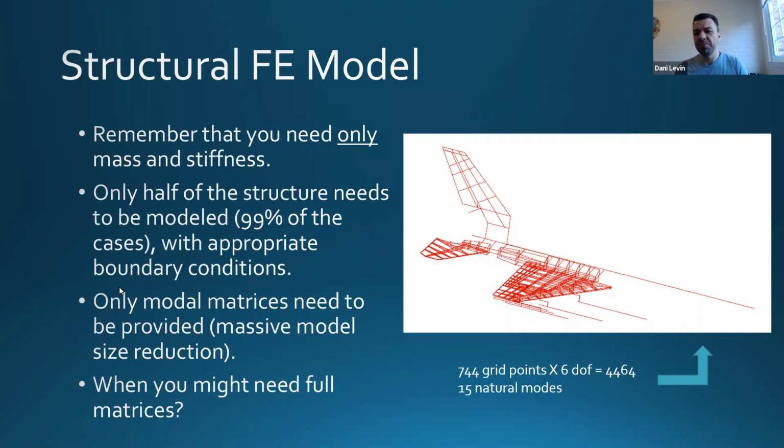Yeah. So beam elements can be generated for any structure. Beam element, the formulation is this. So you have the beam. It's usually 2 nodes, and you provide the moment of inertia and the cross section. So if you can get those from, for example, your CAD model, this beam will represent your fuselage just fine. Of course, with the limitation that it will be only in bending and maybe in torsion, and that's it. You won't get any localized stresses from this model. Okay, was this good? Yeah, it was good. Thank you.